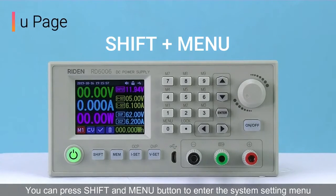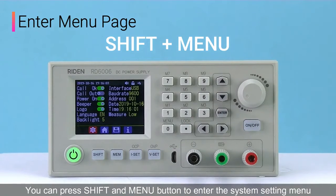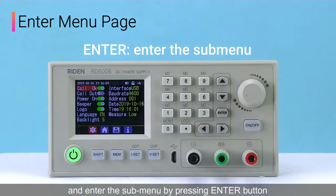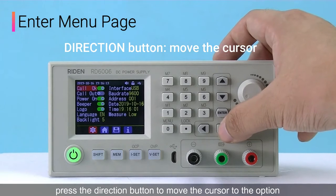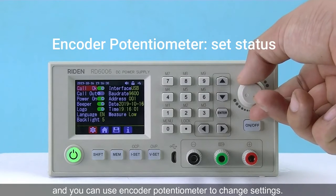You can press Shift and the menu button to enter the system setting menu, and enter the setup menu by pressing the Enter button. Press the direction button to move the cursor to the option, and you can use the encoder potentiometer to change the settings.